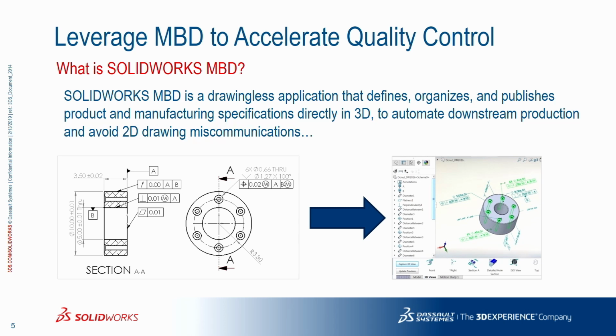And with the SolidWorks MBD tool, you're going to be able to organize that in a comprehensive way, create 3D views, maybe show all the different stages needed to manufacture a particular part. And then you're going to be able to publish that in a format that is easily shareable with everybody in the company. So we, for example, support 3D PDF that pretty much anybody can open, even on an old machine. And you can even export all that to an eDrawings file with all the 3D views, PMI, and all that.